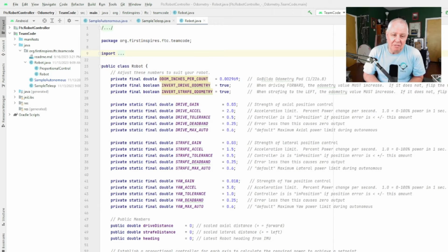So we're actually requesting a speed from the motors, and if the motors don't reach the speed that we want, they will increase their power to achieve it. So even though the proportional controller may be just requesting a very small velocity, the motors will ensure that the robot moves like that.